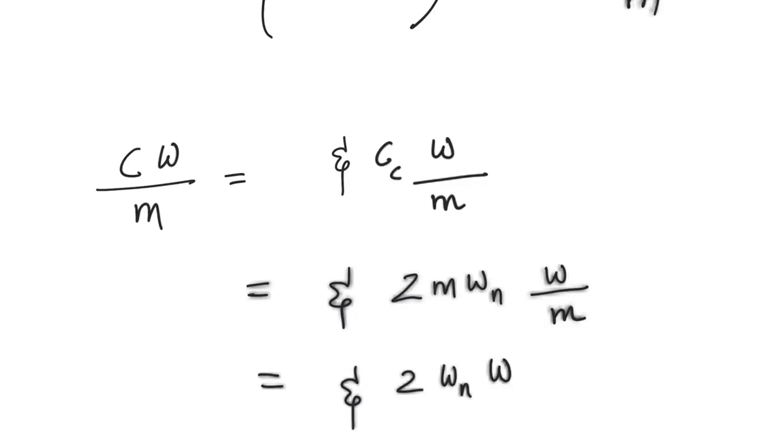So the amount of damping present in the system can always be written as the damping factor times the critical damping coefficient. So that is what we are done here. Then the critical damping coefficient for a single degree of freedom system can be written like this, 2m omega n. So finally this particular term over here can be replaced with this.